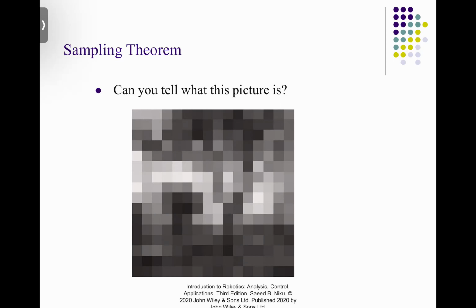What I'm going to do is take snapshots of this signal. If I take a snapshot here, here, here, here, here, and here, and basically plot that data, then I have some crude representation of this periodic signal. It's not accurate, but at least I have the data on the highs, lows, and transition points.